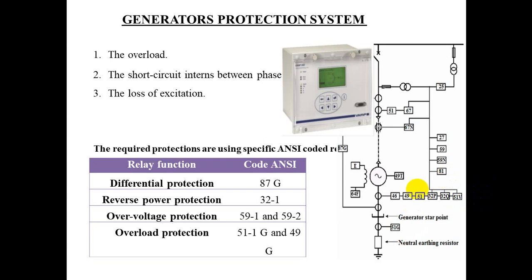Overspeed protection. While it is the general practice to provide a mechanical overspeed device on both steam and hydro turbines, which operates directly on the steam throttle valve or main stop valve, it is not usual to back up this device by an overspeed relay on steam driven sets.